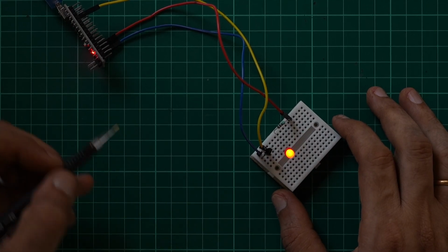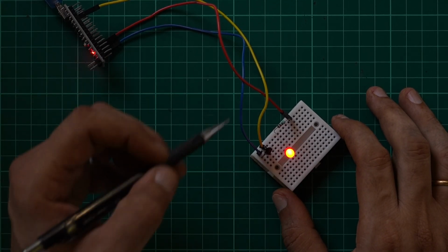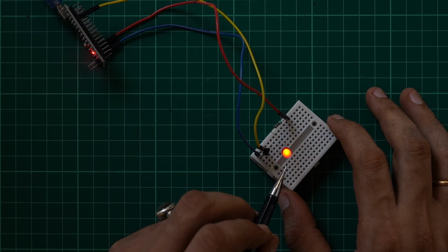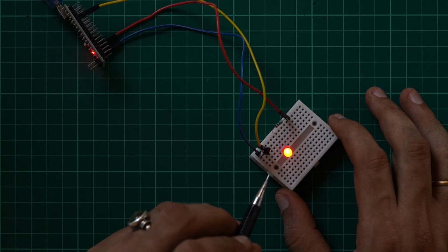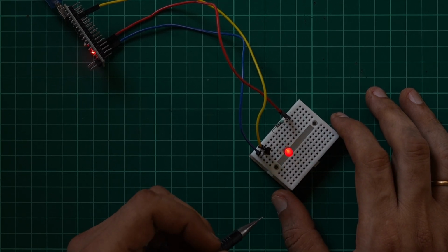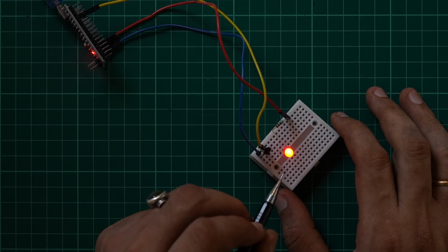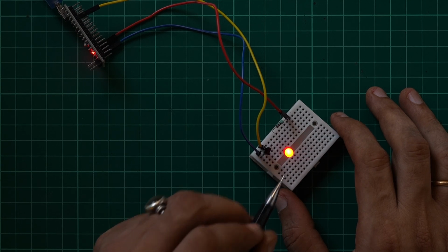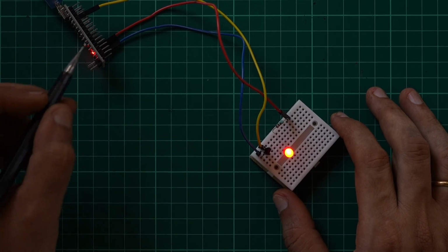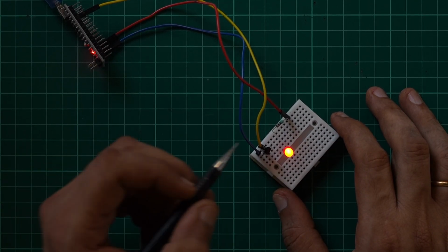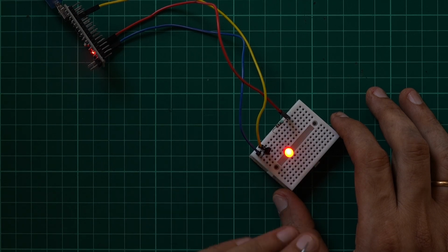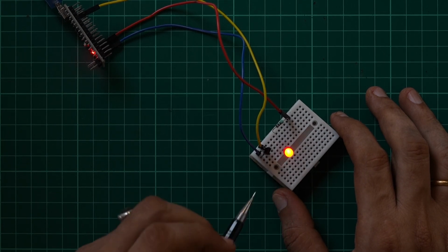So because I am sending a PWM signal over here, you can see that the intensity of the LED is slowly increasing and then decreasing, and it continues to loop through that. It's slightly tricky to see that effect on the LED, because light emitting diodes are current operated devices, and right now I'm just controlling the voltage. So there is a very sharp decline quickly, and then it reaches saturation very quickly.